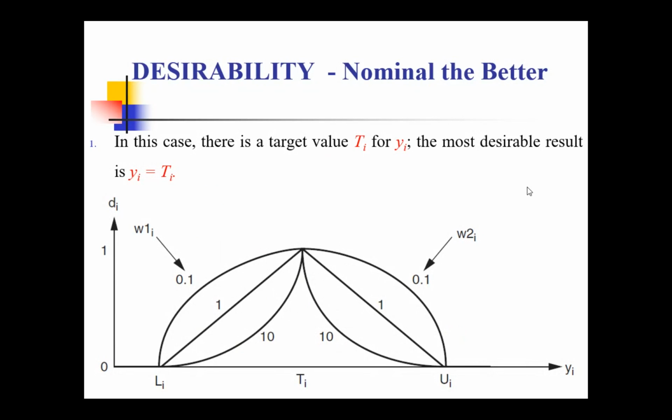In a turning operation, we are going to construct 3 outputs: flank wear, surface roughness and material removal rate. The flank wear should be the lower the better. The material removal rate should be the higher the better. Now the surface roughness I am going to set as a target. I will explain this during the hands-on training. So I am going to set it to a target value, make all these settings, and find out an optimum condition. That is also possible in this.